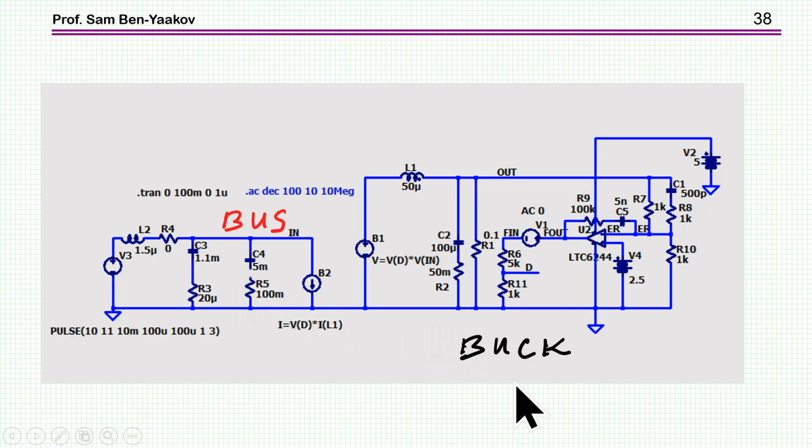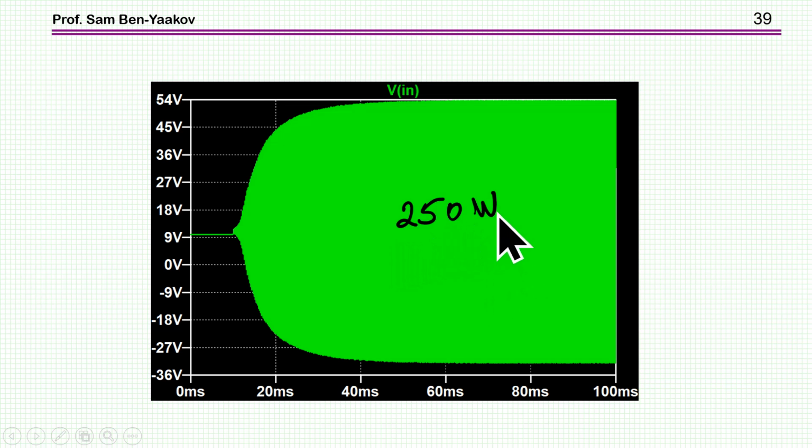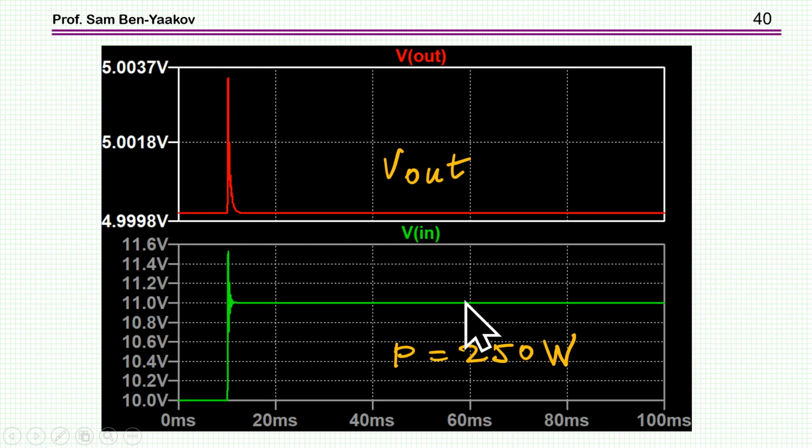And now I'm going to show this in a real simulation. This is again the buck converter, which I've put here for this purpose, in closed loop. And here is the damper. First of all, I'm going to run it without the damper and then connect it and see the difference for this particular case. You see at 250 watt the whole thing is oscillating. Again, there's a lot of sinusoidal signals here. And here I see what happens when I have the damper at 250 watt. There is an overshoot here.